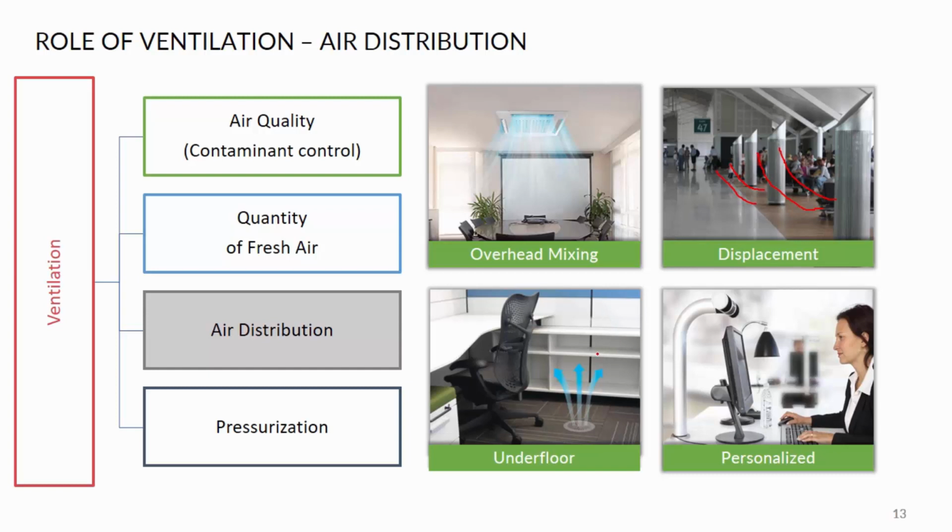This air then displaces the existing hot air and exits the room through the ceiling grills, taking advantage of buoyancy. The next ventilation strategy is the underfloor air distribution system, which is designed to take advantage of both mixing as well as displacement ventilation. Conditioned air is supplied here from the underfloor plenum and existing air is exhausted from the top. The unidirectional flow is maintained here.